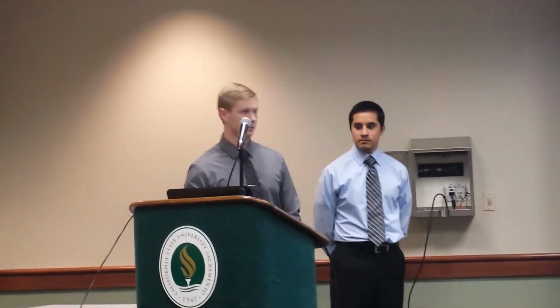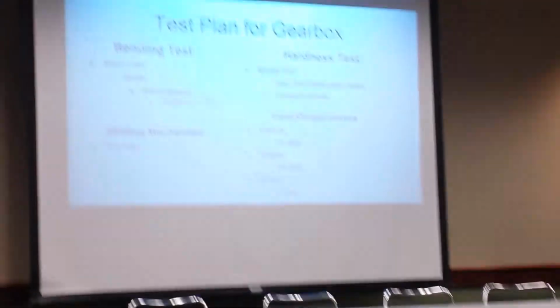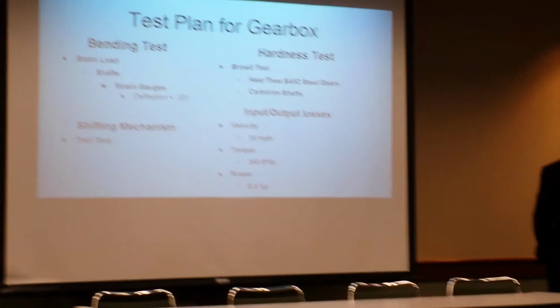So, in order to test all this out, I'll send it to Justin with the test plan for the gearbox. So we have 4 different tests that we will perform. First is the bending test to see that the deflections are less than 1/1000th of an inch at the gears. The next will be a hardness test. We're going to do a Brinell hardness for the gears that we will heat treat and the shafts that we will carburize.